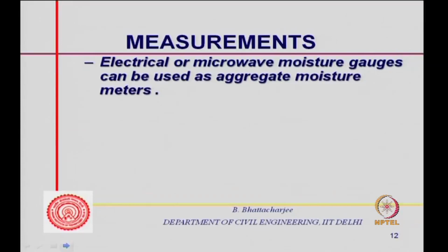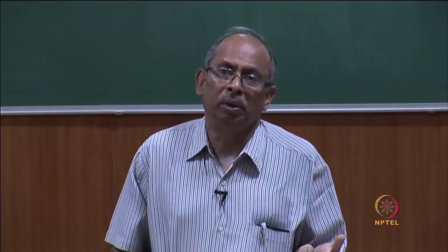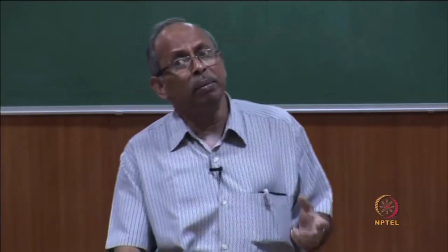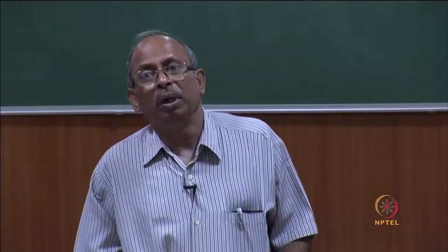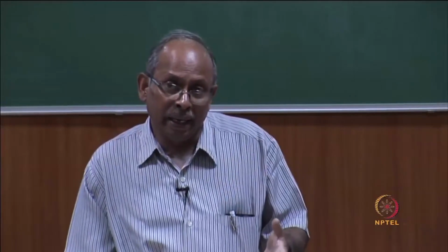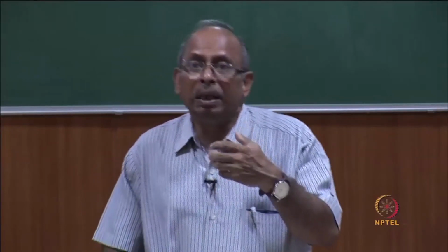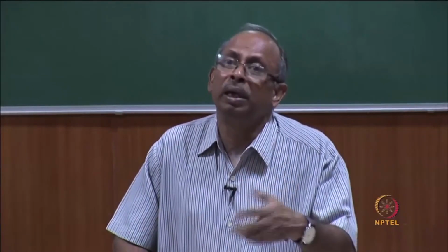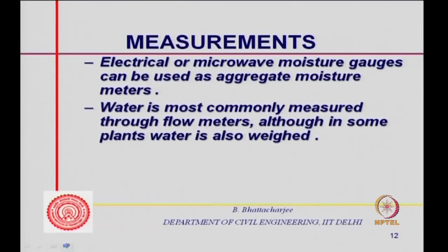Moisture gauges are usually of the electrical resistivity type, but microwave moisture gauges are available, which you just insert into the aggregate, and it will tell you the moisture content. It is desirable that the moisture content of the aggregates is measured all the time and corrections are applied in your mix proportion, because added water will then be less, since some moisture is there in the aggregate, and the total aggregate quantity will be more, because the aggregate contains moisture. So, if you have SSD condition aggregate, you have to adjust the quantity depending upon the moisture condition, and therefore moisture should be measured all the time.